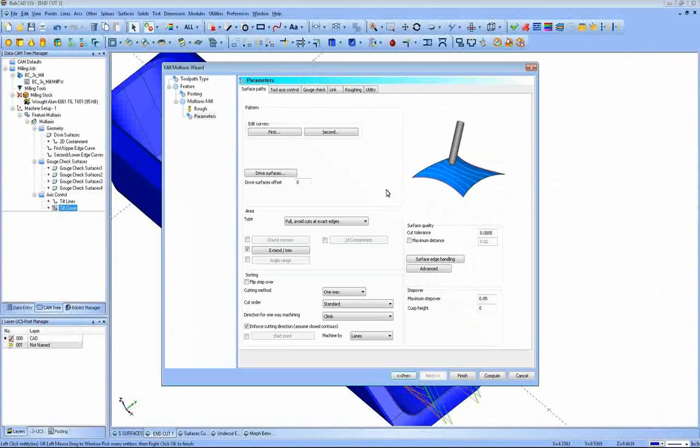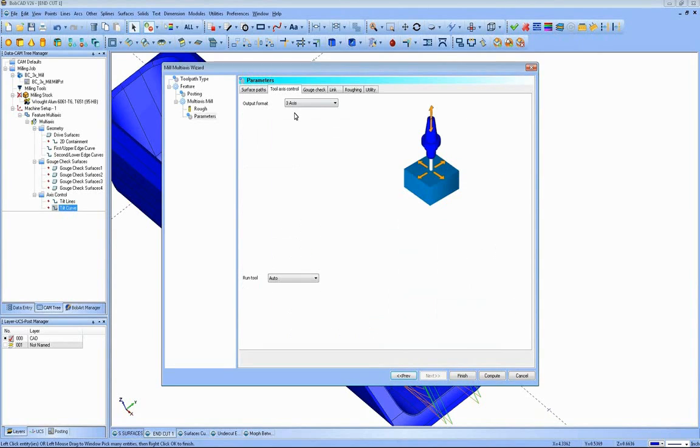And it's going to try and morph from the top shape to the bottom shape along those drive surfaces. I did full cuts, avoid edges. I even extended it out a little bit farther. One directional climb mill and a 50,000 step over. I outputted it as 3 axis.